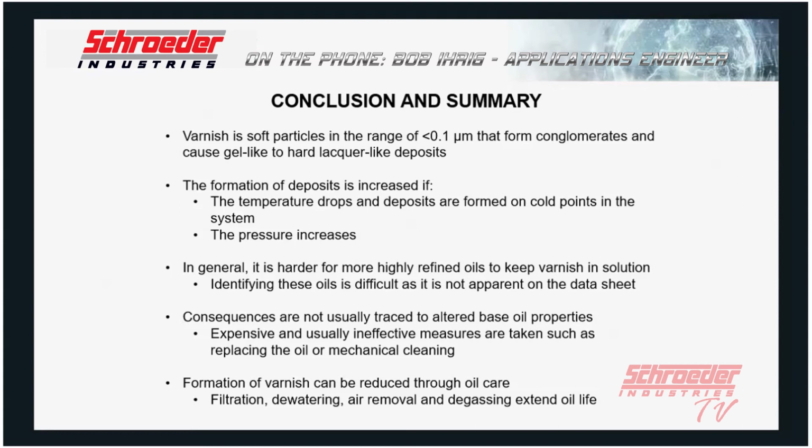We also talked about, in that same respect, that the more highly refined, the less conductive in most cases, like Group 2 oils, and that is a significant contributor to oil degradation, as well as consequences that are not usually traced to altered base oil properties, which can lead to expensive and usually ineffective measures, such as replacing the oil or mechanical cleaning.